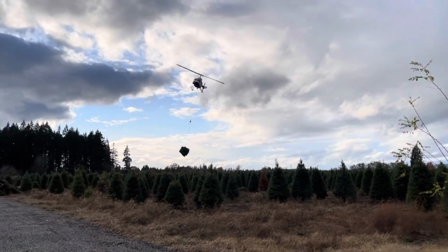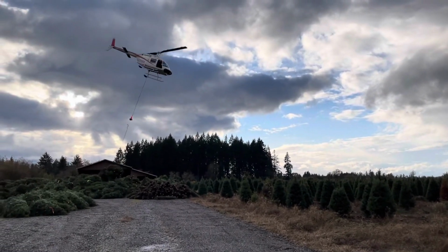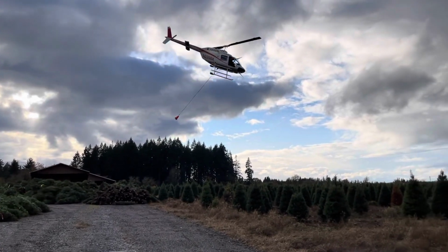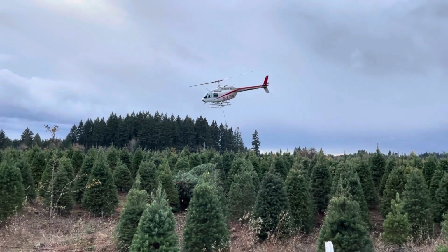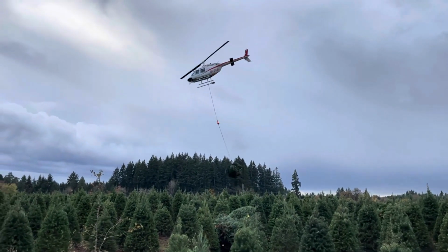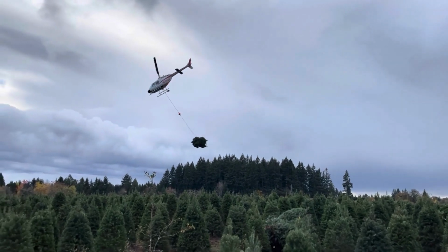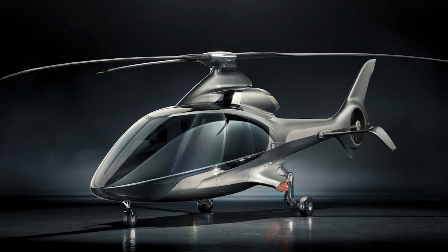Parasite drag is defined as drag caused by non-lifting components of the helicopter, such as the fuselage, the landing gear, or any external equipment, police camera balls, or external spotlights. Parasite drag increases with the square of the helicopter's speed. This means as you fly faster, parasite drag becomes the dominant form of drag. A more streamlined helicopter shape reduces parasite drag. Anything that sticks out into the airflow, like antennas or skids, increases the parasite drag.